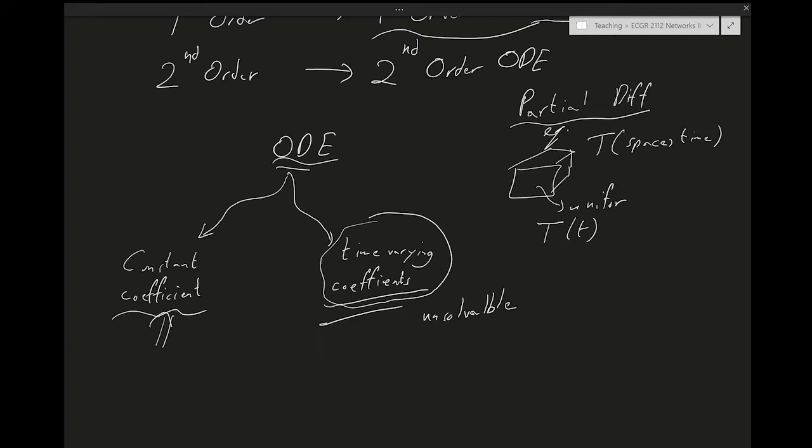So we said transient analysis is concerned with analyzing what happens if there is a change in the network. Either the voltage changes suddenly, or the network itself changes suddenly due to the throwing of a switch. So it's a special kind of change. It's not a change that's occurring all the time. If we have a change that's occurring all the time, we end up with a time varying ODE. That's not what I mean by transient analysis. I mean a change that happens suddenly, and then things get steady after a while. It's a sudden change in the network.